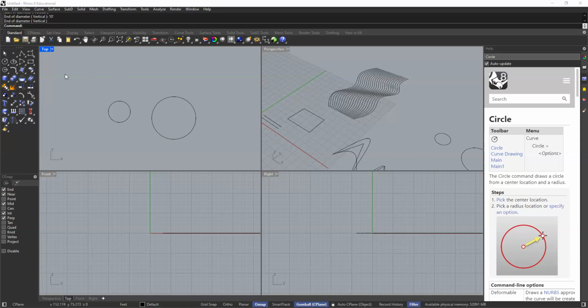Going back to this radius, so let's go ahead and click on this icon right here. Again, the center, by default, this one is to specify the radius. Okay, I could click in the center, and notice that when I click in the center, my options up here change. Let me undo or escape that just so that you can see that. And this is true for a lot of commands. So I'll click here, and right here, it's asking me to find the center of the circle, and I have some options. So we can still change if we want to find it from a 2 point or 3 point or tangent. But if I go ahead and click on the center, watch what happens up here.